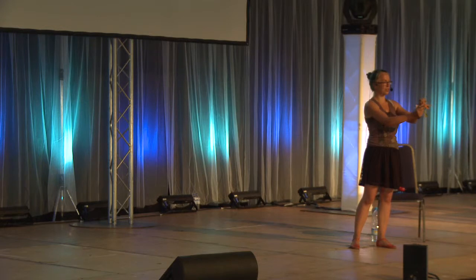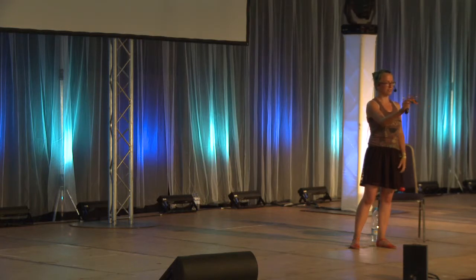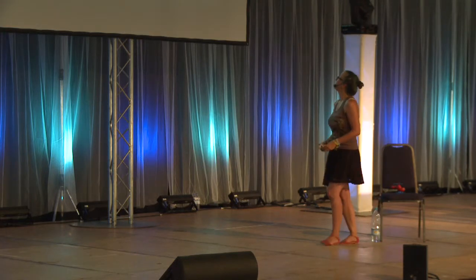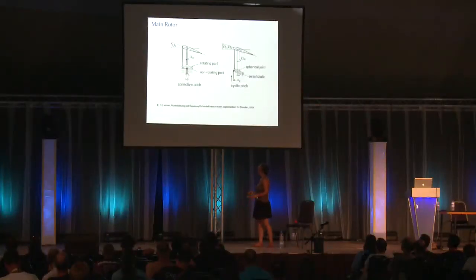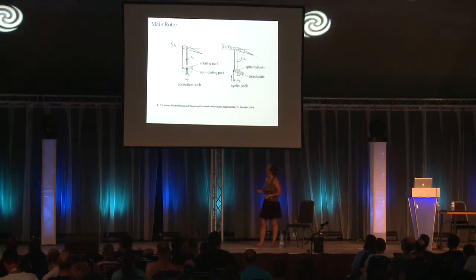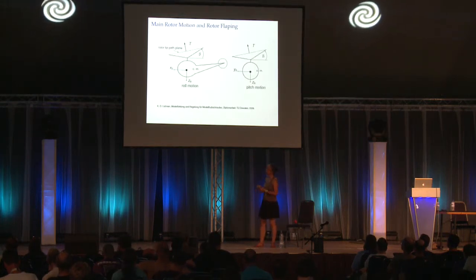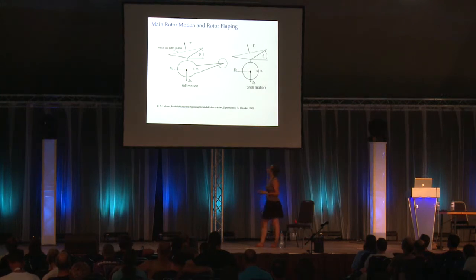You can actually turn this thing, which enables the helicopter either to roll or to pitch forward by simply tilting the whole plane of the rotors. It's a bit unstable, you can't see it in the back. And furthermore, what happens with helicopter blades, they are pretty flexible. It's a pretty important thing for helicopters because that enables them to fly.